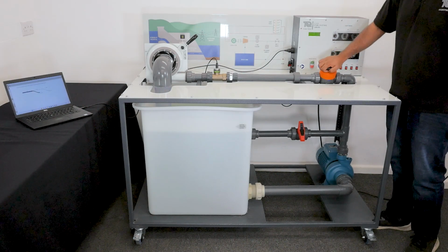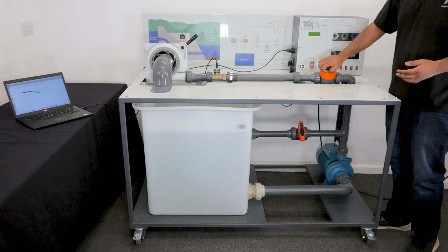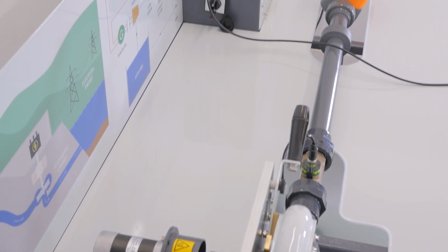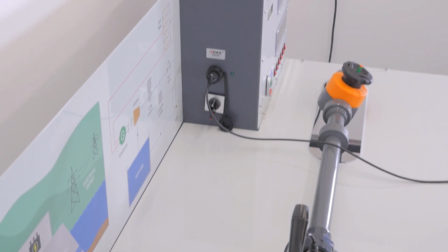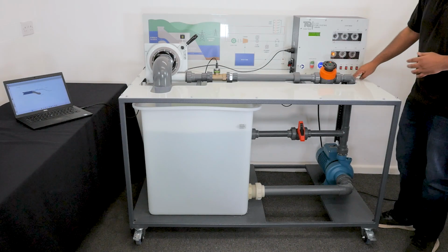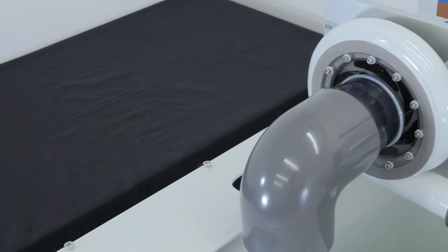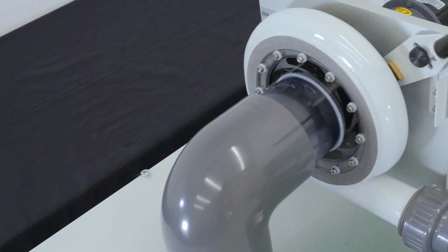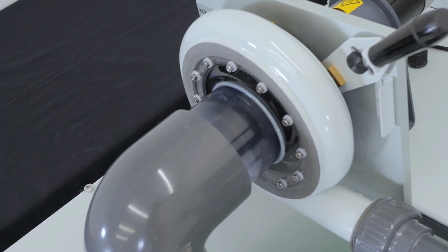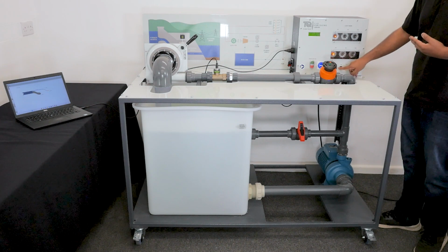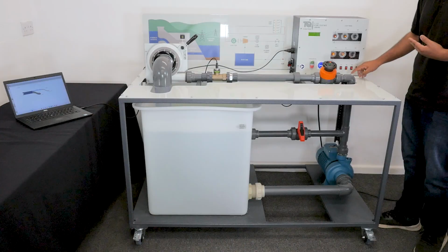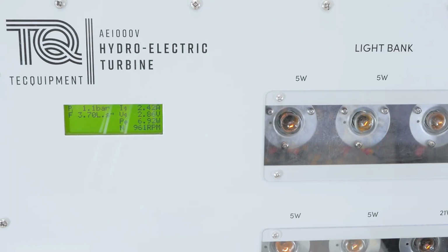At this point it will be very noisy due to the differential pressure, but this will reduce as the flow rate increases and thus flow pressure becomes stable. Do this continually until the valve hits the maximum open position, and then you can start engaging the load. Now we can see the speed has dropped and the power has increased slightly as we have loaded the generator to obtain more power. Now we can increase the load by switching on lamps one after another and see what's happening to speed and power generated.